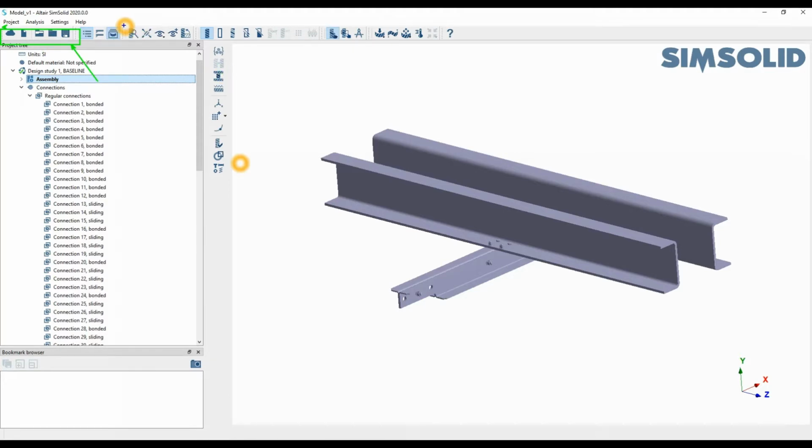With this part here, you have all of your different views and your icons. Based upon the views that you have, you can specify to fit everything to page. You can expand your window, you can zoom in, and you can also look at it from different perspectives, so from the XY plane, ZX plane, etc. Once you orientate your model in different views, you can save it so that it's always saved as a view that you can refer back to.